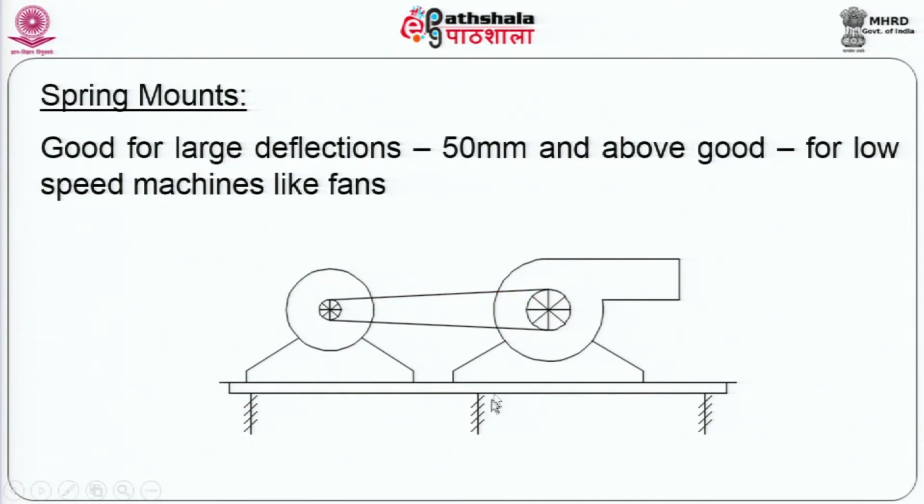As I mentioned in my audio first, basically springs are devices which give you the largest deflection. They are useful for supporting fans which generally run at low RPM. So, if you have a kitchen exhaust fan from a basement restaurant sitting on the roof and the flat below or the office below is tending to make noise, all you have got to do is on the base support it on springs which are flexible enough to be able to give you the static deflection of the disturbing frequency.